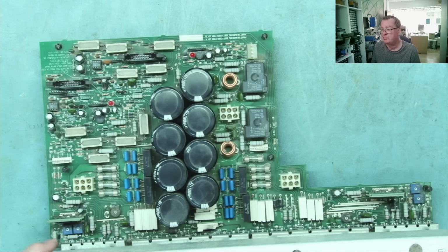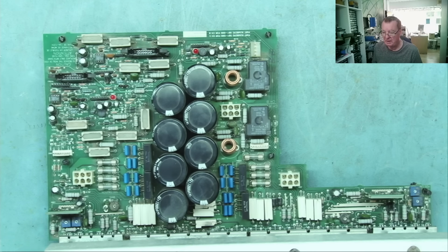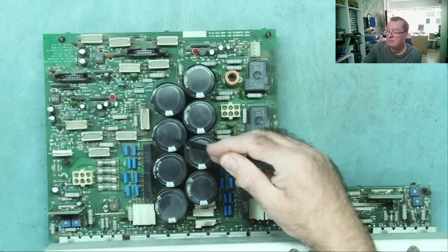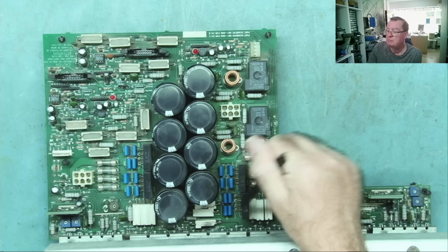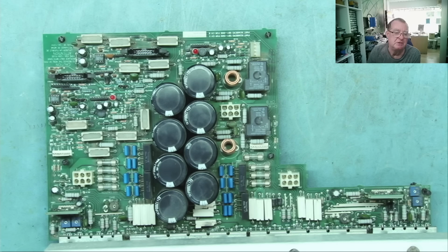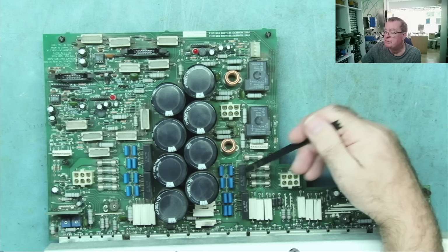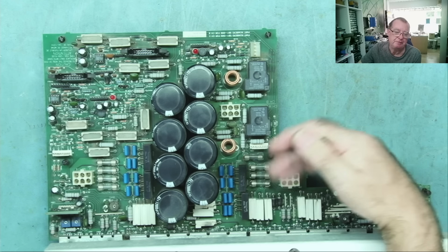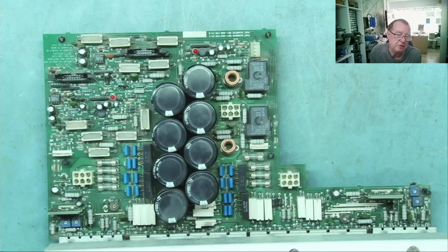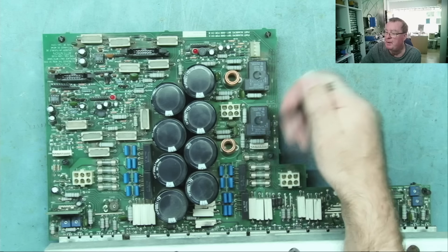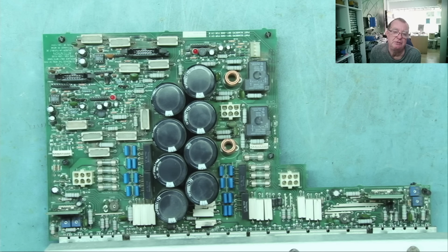So the voltage is coming in via a linear transformer running at 50 hertz or 60 hertz, depending where you live. That's rectified by the bridge rectifiers we see here, and the output of those rectifiers is smoothed by the capacitors. Because effectively the rectifier doubles the frequency of the incoming mains, these are running at 100 hertz or 120 hertz. And these sort of capacitors generally don't fail.